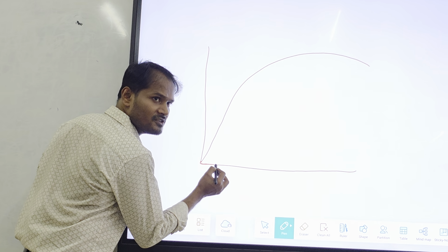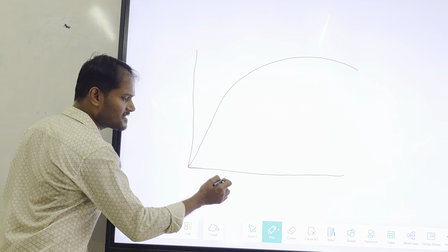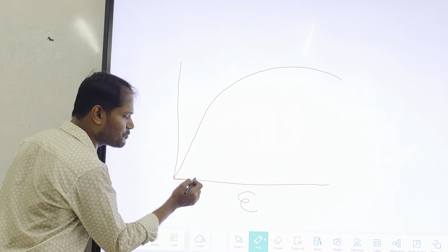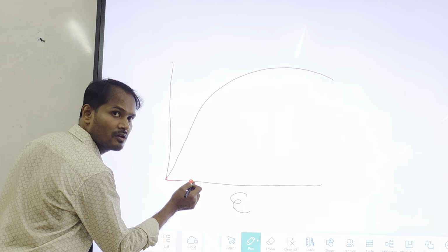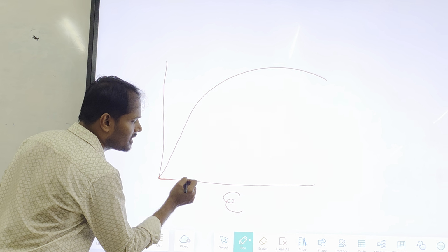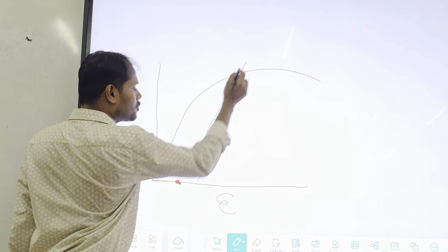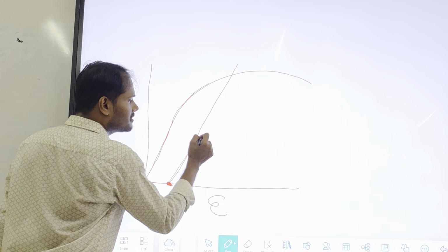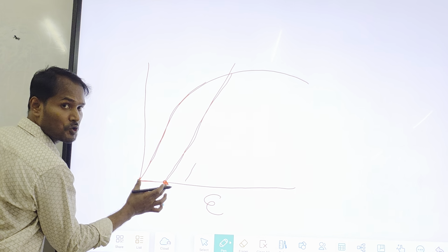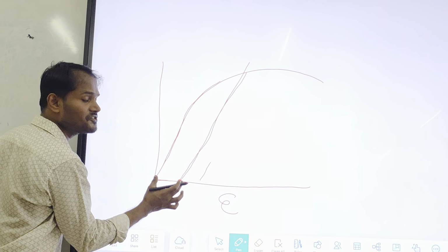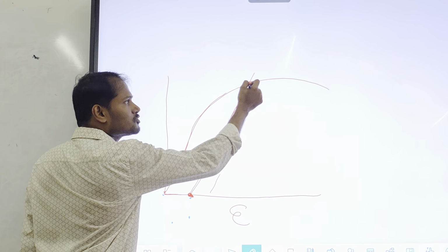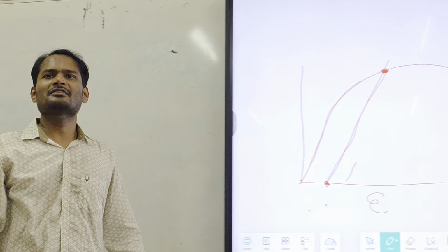go in this direction first and take a point, because this is the strain axis, right? So you have to measure the 0.2% strain. Suppose 0.2% strain is this one. Let it be this distance. You need to draw a parallel line like this to your main curve. This is your main curve. So you need to draw a parallel line like this at this 0.2% elongation, or 0.2% strain actually. So it will definitely cut the line here. So this will become ys. This is not an exact diagram, but you understood this one.